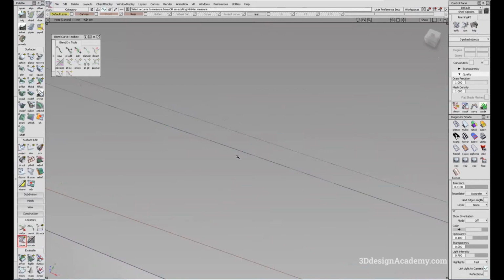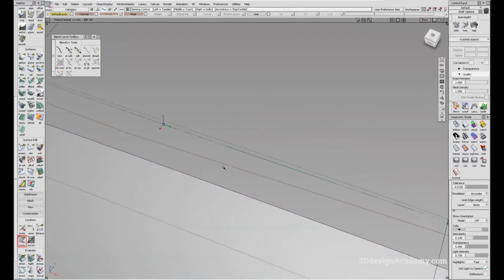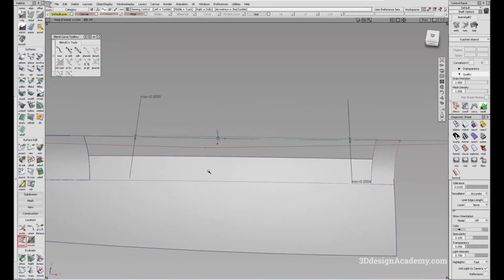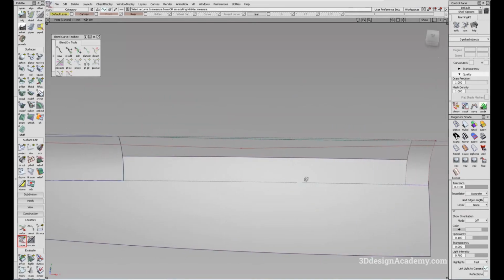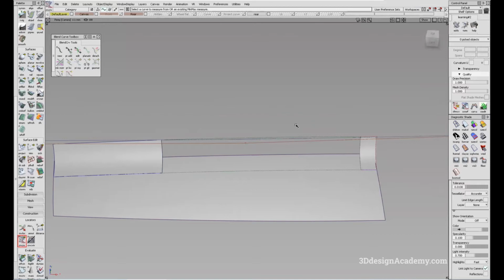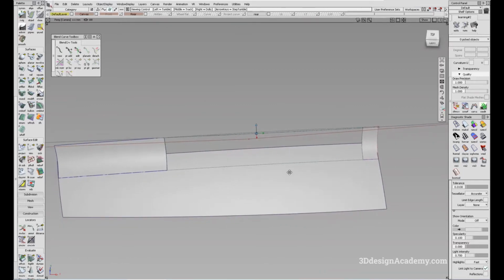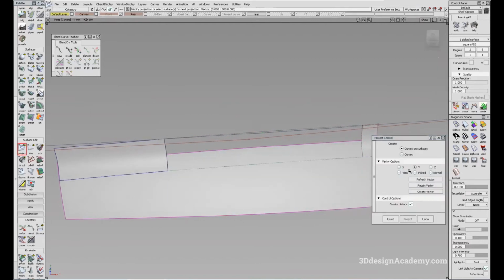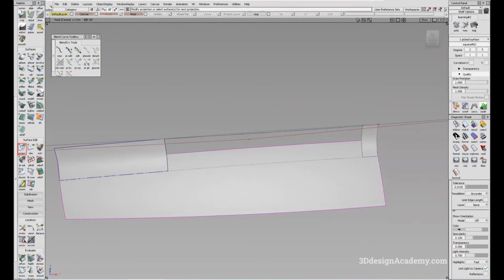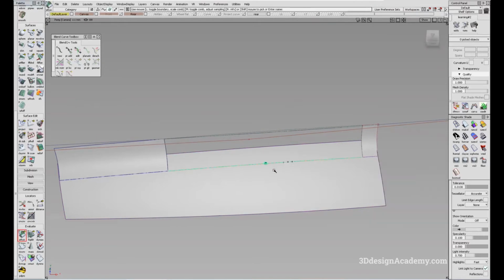So what I'm going to do is I'm just going to do a curve to curve. And looks like it's actually positional. So if that's the case, this actually makes my life really easy. So what I'm going to do is I'm just going to intersect these two pieces, and we won't have to trim anything, trim, convert, and align all the stuff. We don't have to do any of that. So I think I'm just going to leave it like that. So I'm just going to, first of all, project this one, make sure that this is curvature continuous, and it is.